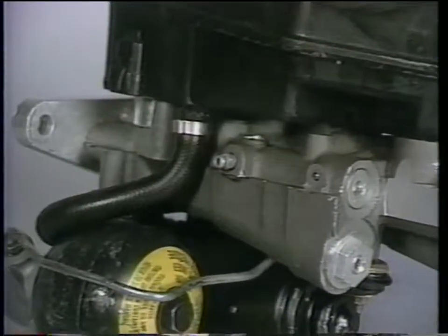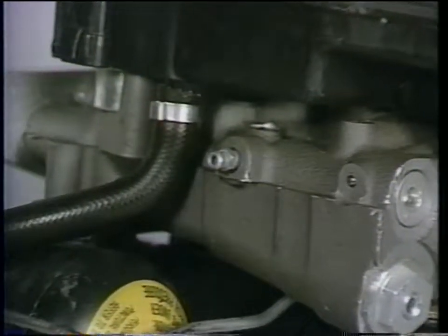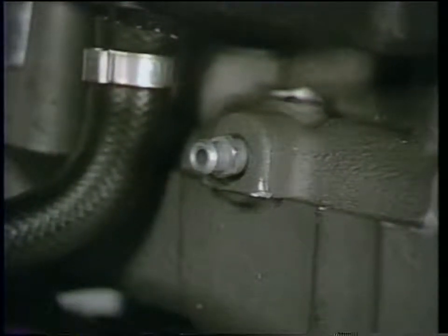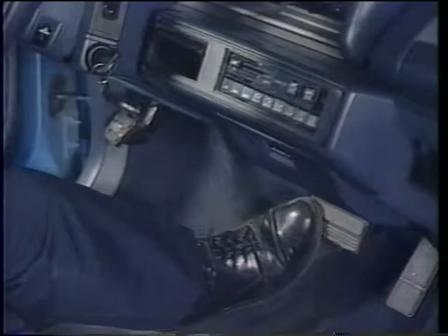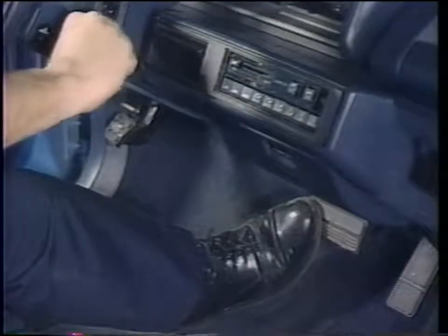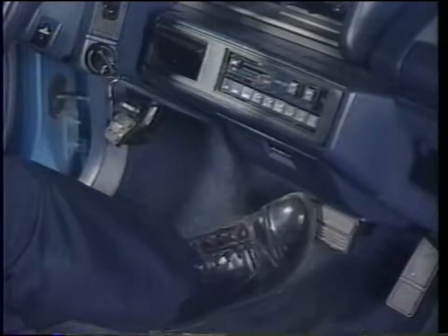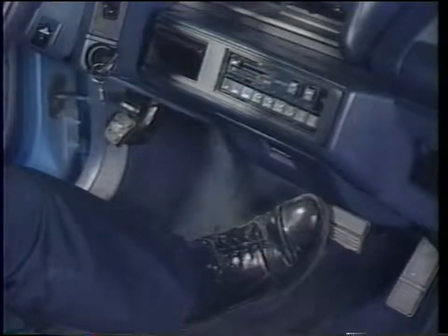After bleeding the rear lines, the isolation valves in the PowerMaster unit are bled by opening 2 bleeder screws on the unit. Light pedal pressure will force fluid through the screws to remove air. Only 1 screw should be bled at a time. Afterwards, depressurize the accumulator again by pumping the brake pedal 40 times with the ignition off. Wait about 2 minutes for the brake fluid to settle. Add fluid as needed to the fluid reservoir. Then reapply pedal pressure and turn the ignition on for 3 seconds, then off. Cycle the ignition on and off every 3 seconds 10 times to complete the bleeding procedure.